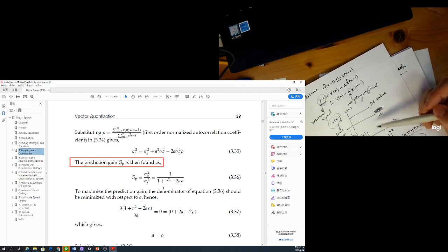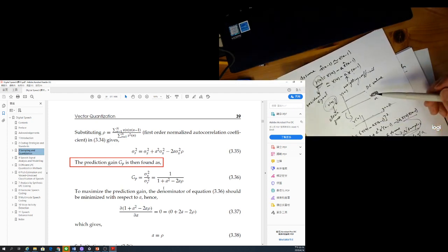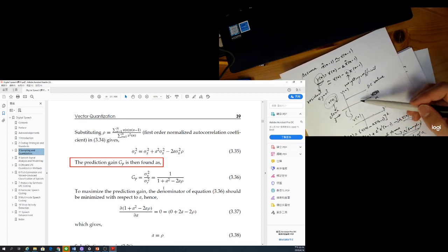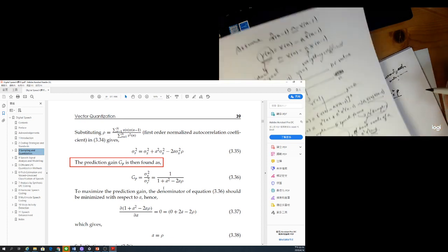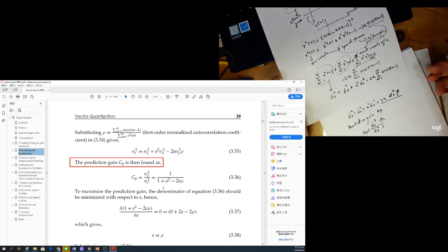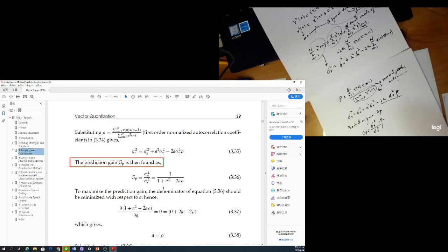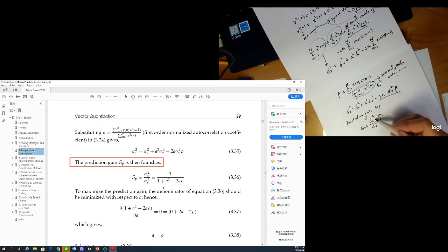If you take a differential, the residual signal becomes 0. So the prediction gain, this one divided by 0, becomes infinite. So your signal entropy will become lower, and that will make your encoding easy. So we define your original signal power divided by your residual signal power, because you already do the prediction.